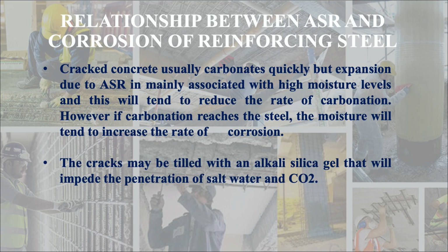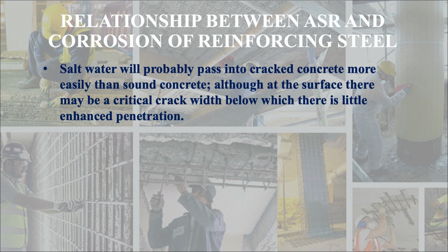The cracks may be filled with an alkali silica gel that will impede the penetration of salt water and carbon dioxide. Next is, salt water will probably pass into cracked concrete more easily than sound concrete, although at the surface there may be a critical crack width below which there is little enhanced penetration.